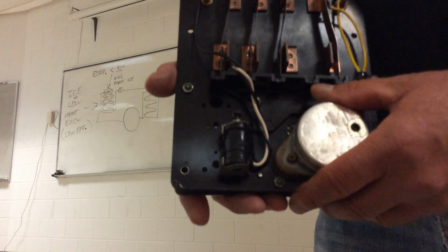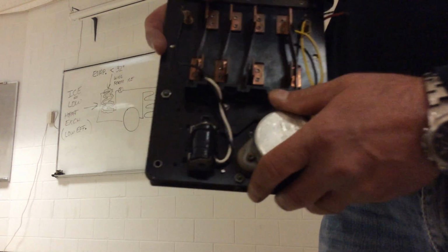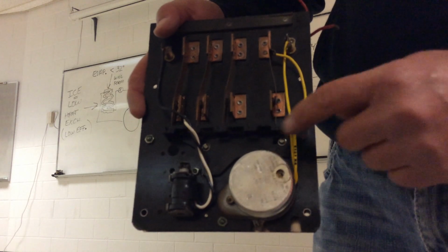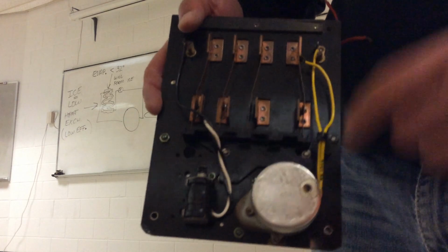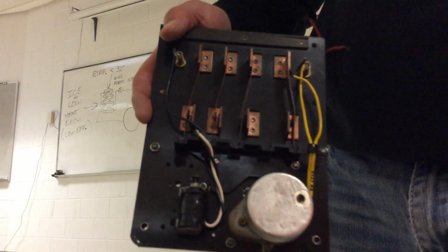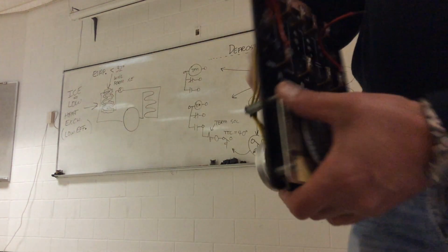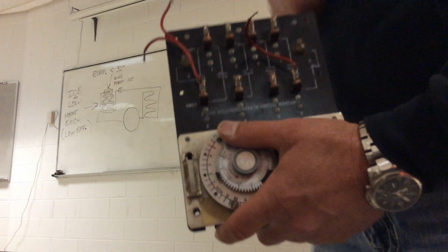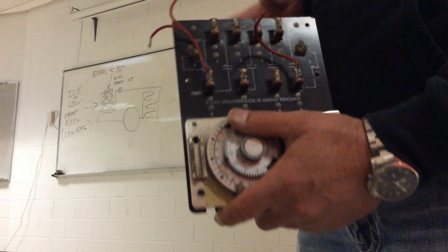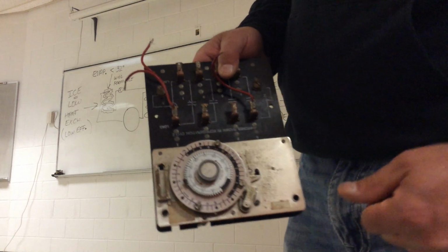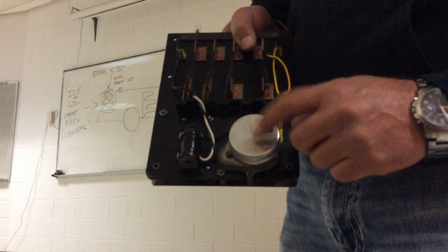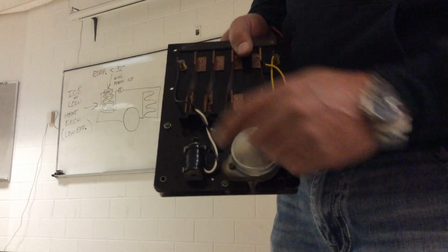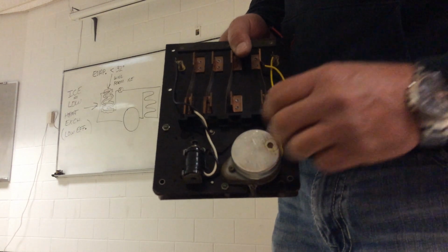So if you're out in the field, you can take these out. These defrost clocks, you can take them apart and look at the components if need be, and know where what component is wired to. But it is a skill that we're going to learn, how to ohm these time clocks out. Okay, I'll say this again in the next video, but the timer motor has the highest resistance out of everything that you ohm out.